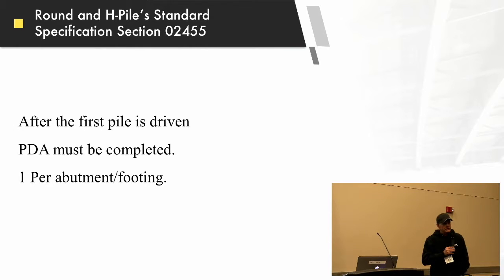But again, that's not for the whole structure. That's for that one abutment or that one footing, because you have to do that each time you start a new abutment or footing, because the soil conditions could change. And that's just, again, all about capacity of the pile, so that in the end our structure is gonna be able to function as designed.